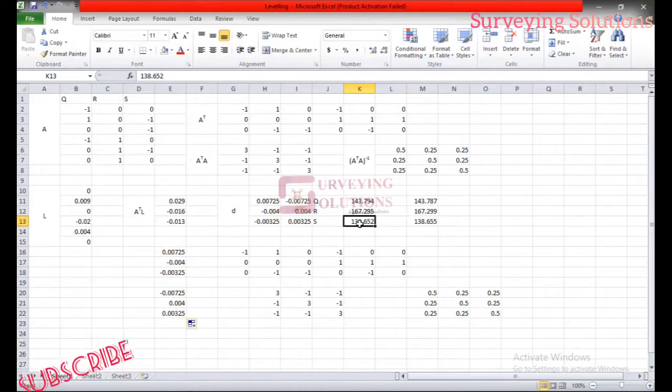These are the observed heights, as we got from the observation. Now, these are the most probable values. How then do you arrive at the most probable value? Since you already know what these errors are, you add this error to our observed height, which is what you can see here.